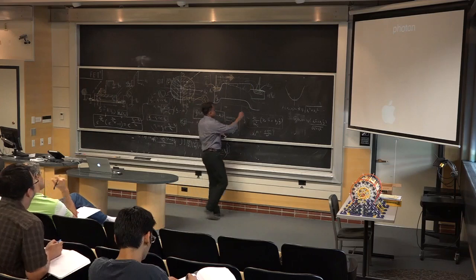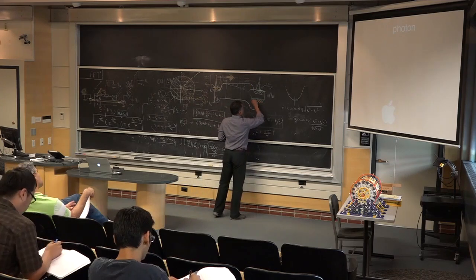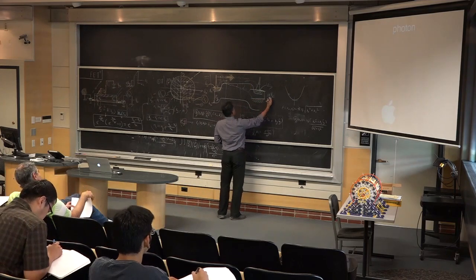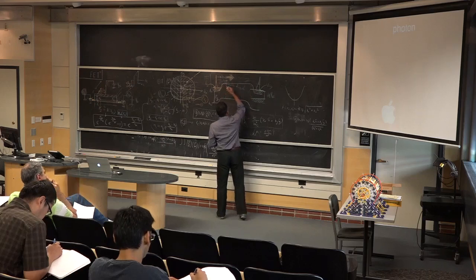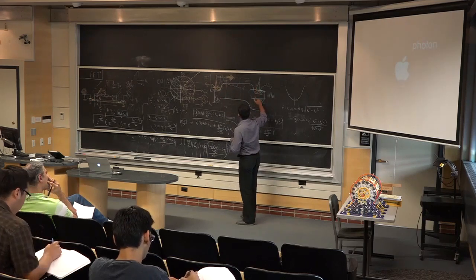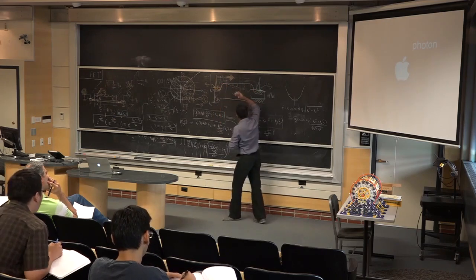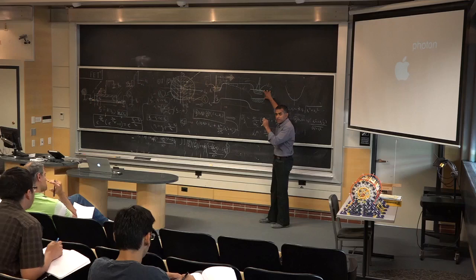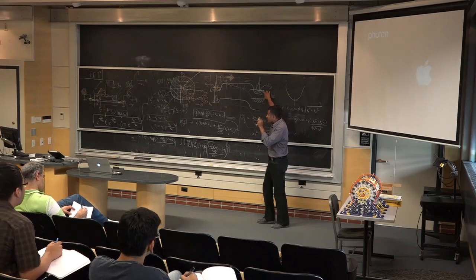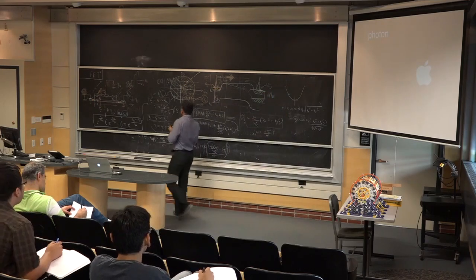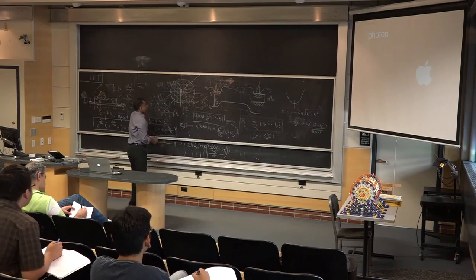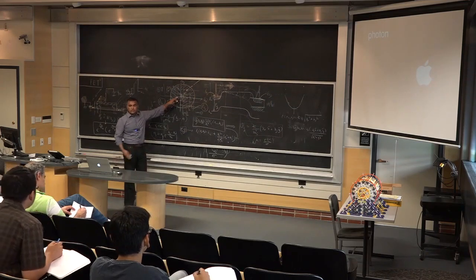The way to look at it now is, look, I have a Fermi level of the source. This source is still trying to inject carriers to go to the left, but you can see immediately that it has a much higher barrier to get over. The barrier height has suddenly increased by how much? By this much, by the applied voltage. The barrier has suddenly increased by quite a bit. Therefore, what's going to happen in this picture? Maybe you can help me.